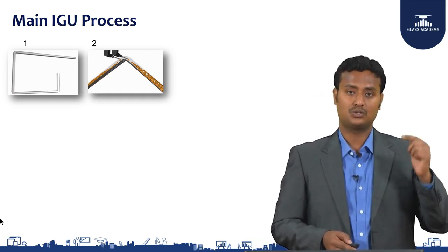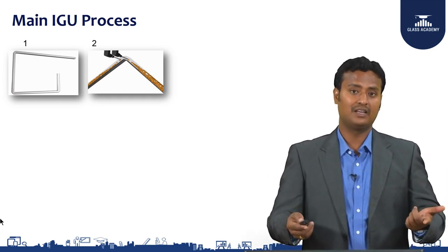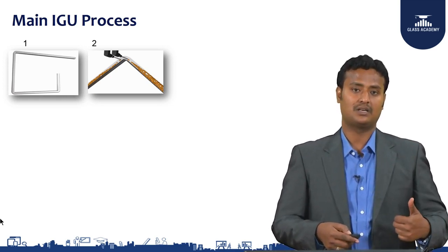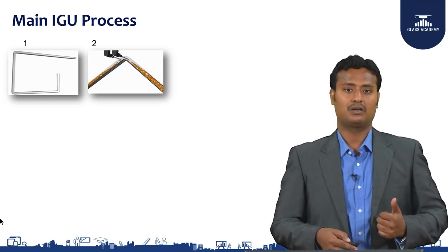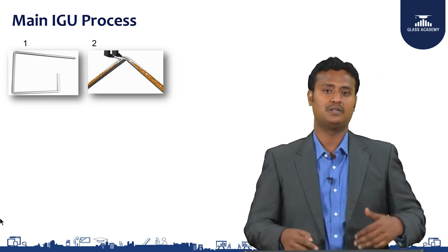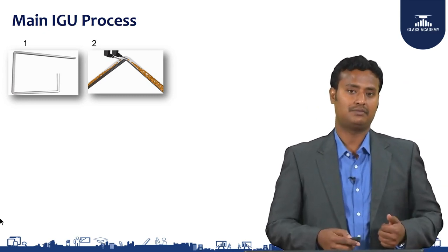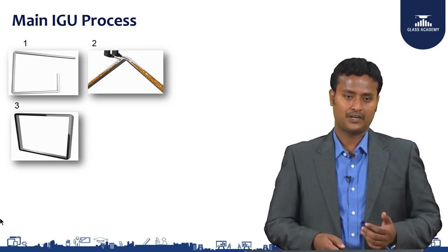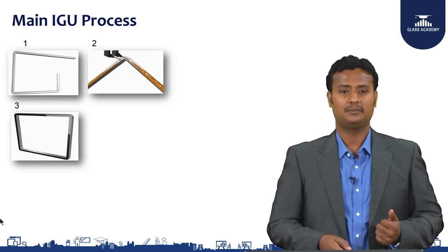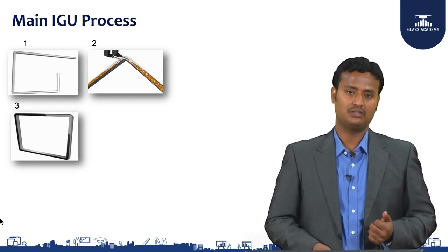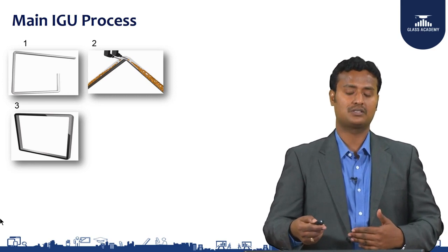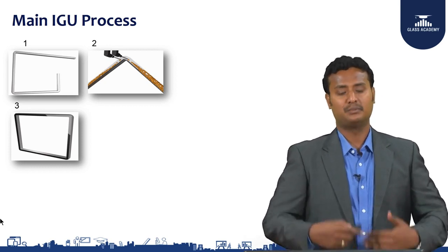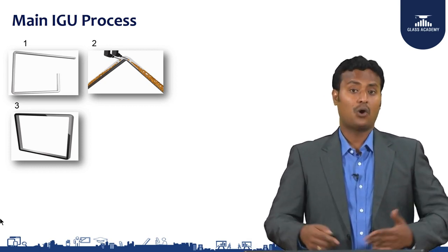So once the hole is done and you have filled the desiccant, you have to go back and fill it with butyl, which is basically primary sealant, to plug it, and then you can go for the next operation, which is frame positioning of the frames on the glass. This is the next step in the IG process, where the frame is taken to the primary extruder machine. It's not joined along with the IG process line.